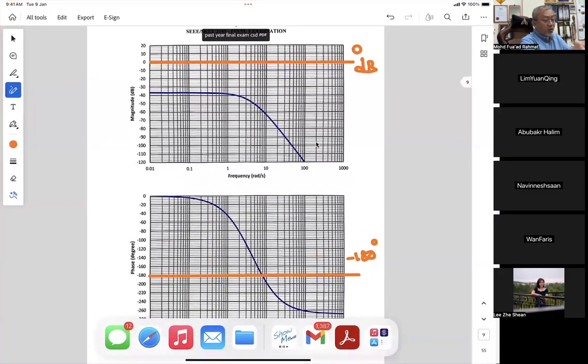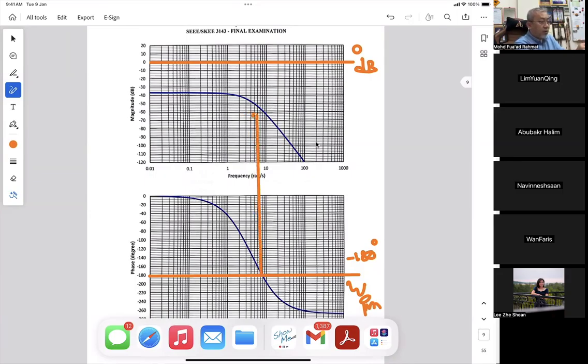Okay. By looking at this, should the answer be only that the poles are at the left, and you can only find omega PM, am I right? Yes. And then omega PM will give you the magnitude negative. So that is the only reason why it is stable. Omega DM does not exist, the gain curve does not cut at 0 dB at all. So only phase.